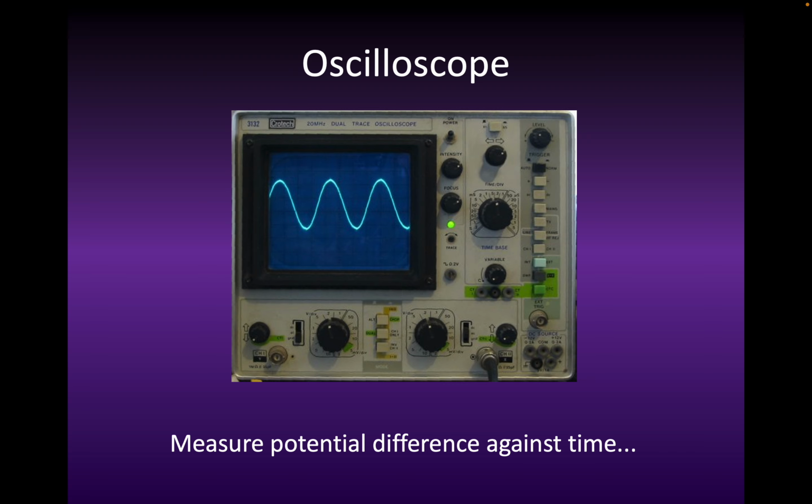Okay, so going back to the AC wave, up above the center line is positive voltage, and below the center line is negative voltage. So actually the average overall, if you think of it in terms of positive and negative, would be 0 over a whole cycle, but that's not how we measure the voltage of an AC power supply.